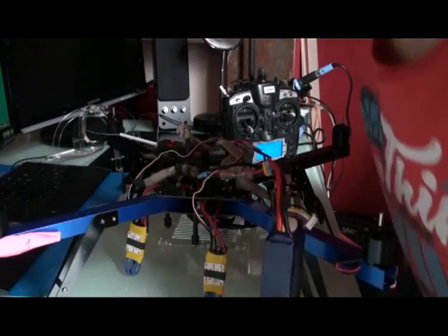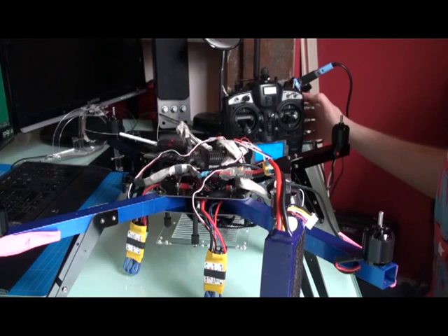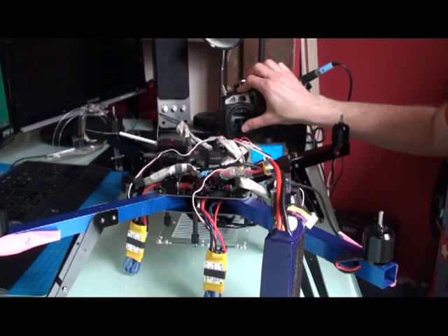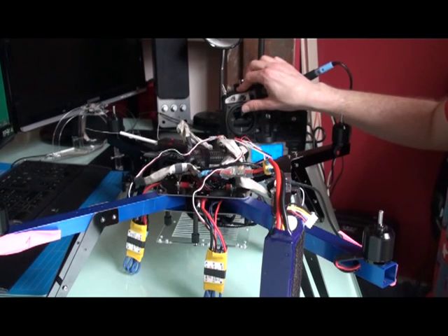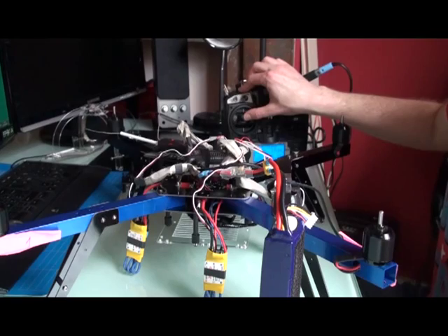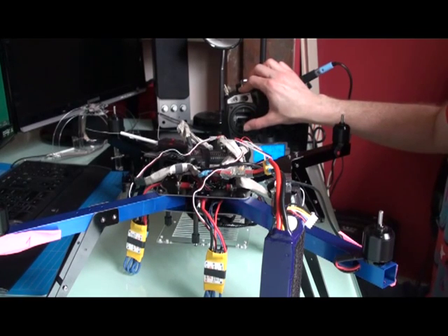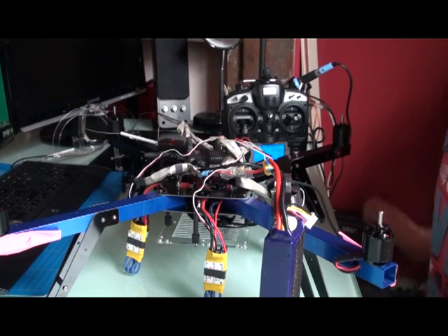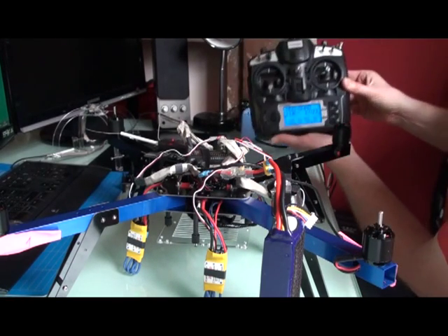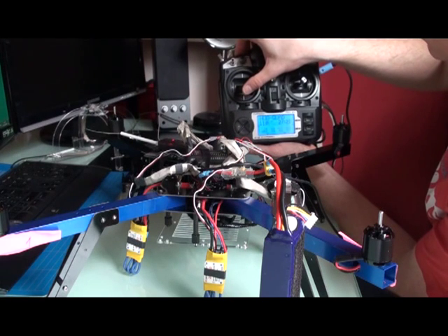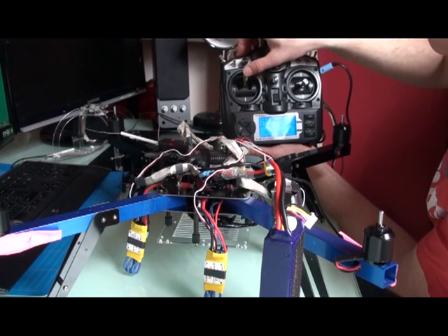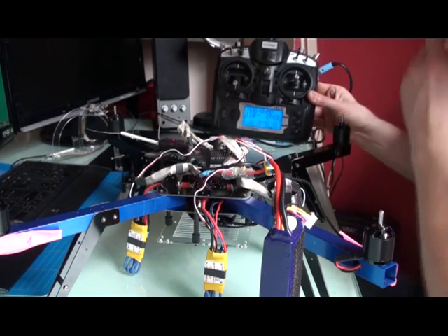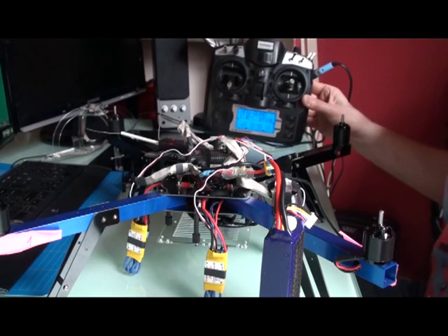So now I am at step 6 of calibration. I have calibrated the ESCs, and when I move the throttle stick, we hear very well that I have a progressive throttle. So this is at calibration moment, when the signal of the transmitter is directly transmitted to the ESCs.